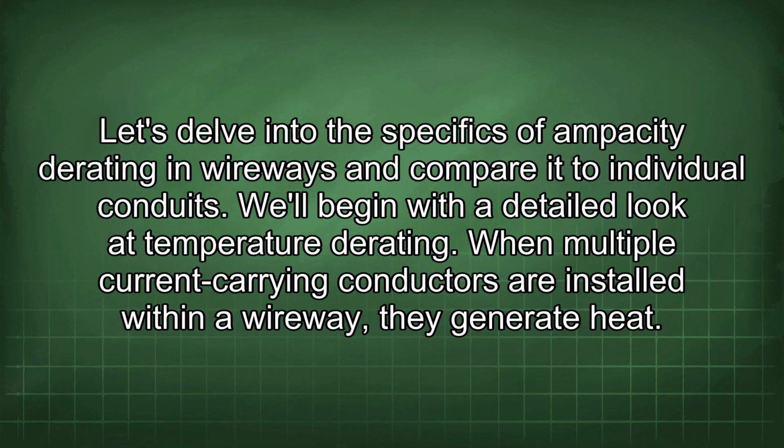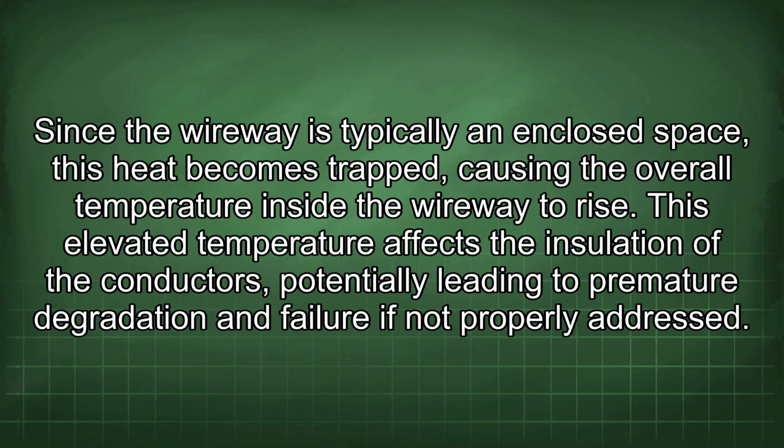Let's delve into the specifics of ampacity derating in wireways and compare it to individual conduits. We'll begin with a detailed look at temperature derating. When multiple current-carrying conductors are installed within a wireway, they generate heat. Since the wireway is typically an enclosed space, this heat becomes trapped, causing the overall temperature inside the wireway to rise. This elevated temperature affects the insulation of the conductors, potentially leading to premature degradation and failure if not properly